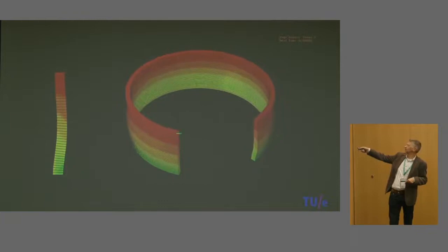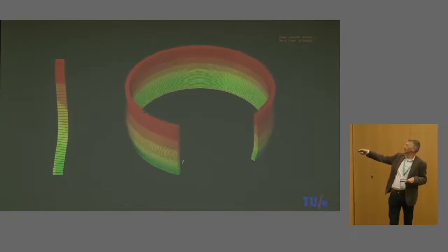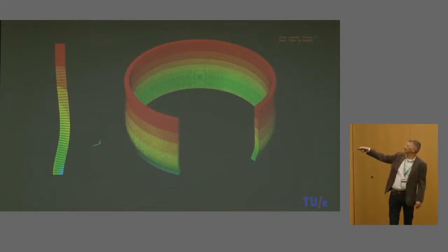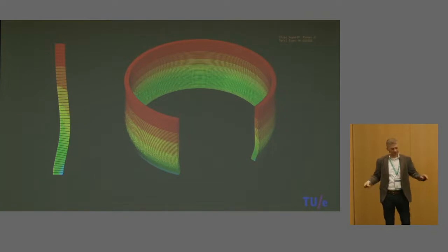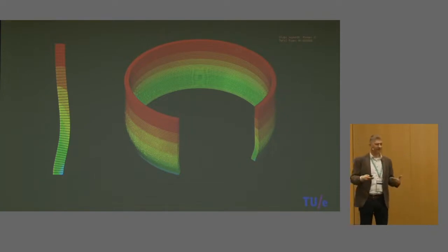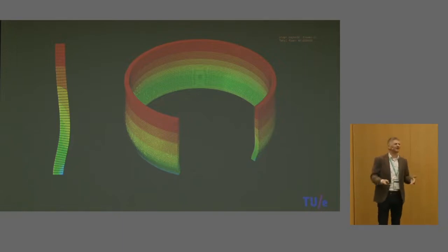Of course, the force is low here because there's no pressure on site, and the force is high because the dead weight is on the top. It's not about that, it's about the shape. You can see the same buckling shape. The column that you saw previously is not failing because the wet concrete is not strong enough. The concrete was just failing because it buckled. It is an instability problem. It's just a structural problem that comes with stiffness, not with strength, and with shapes.